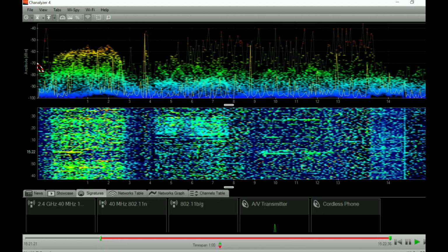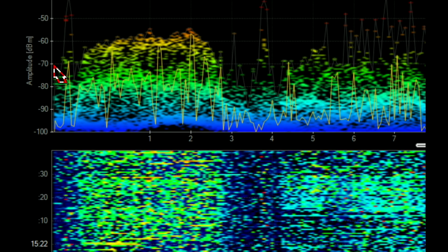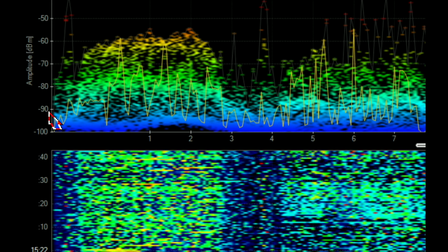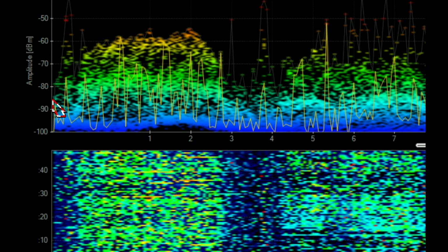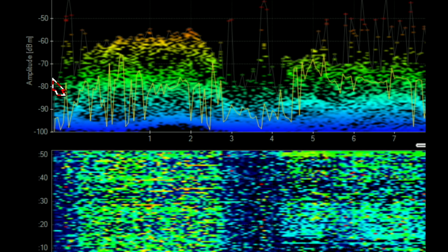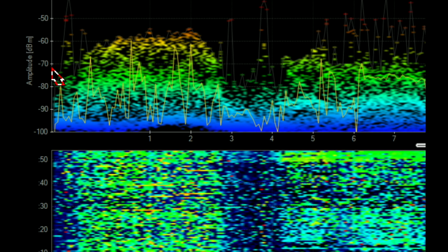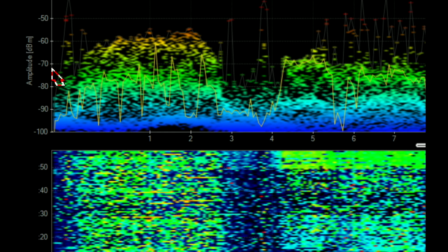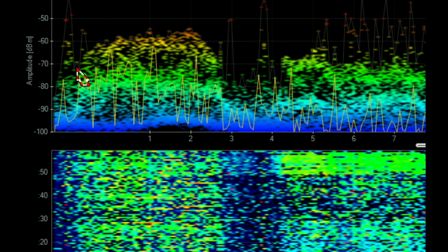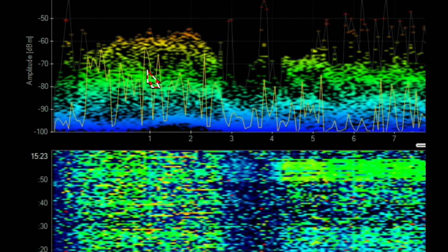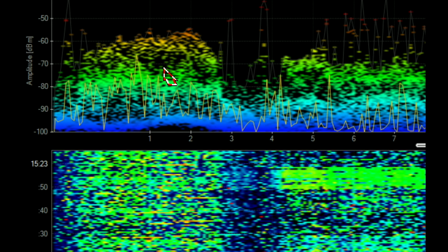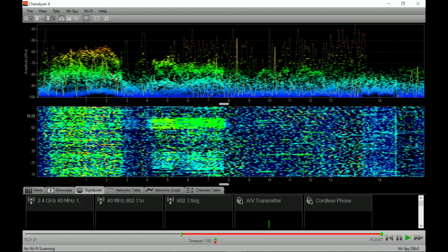The signal is good as long as it is 20 dB away from the noise. So even -70 can be a good signal as long as the noise is not above -90. So the distance here should be 20 dB, which is a factor 100. If you have a very good receiver, then 17 dB is good enough, which is factor 50. 3 dB is always half or double, so that's what you can see here.